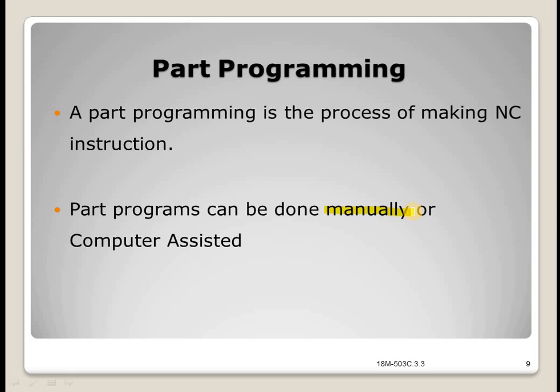We shall divide manual programming jobs into two categories: point-to-point jobs and contouring jobs. Except for complex work parts with many holes to be drilled, manual programming is ideally suited for point-to-point applications. On the other hand, except for the simplest milling and turning jobs, manual programming can become quite time consuming for applications requiring continuous path control of the tool.